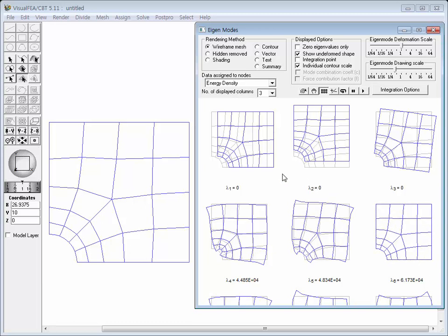As mentioned earlier, the rigid body modes are essential components for proper displacement behavior. On the other hand, the rigid body modes correspond to linear dependency of finite element equations, and therefore, should be constrained for unique determination of the displacements by finite element analysis. The rigid body modes are constrained by assignment of boundary conditions.